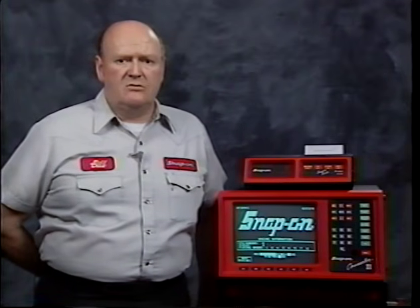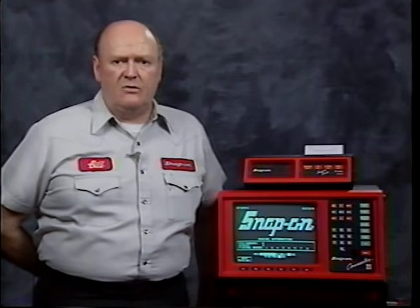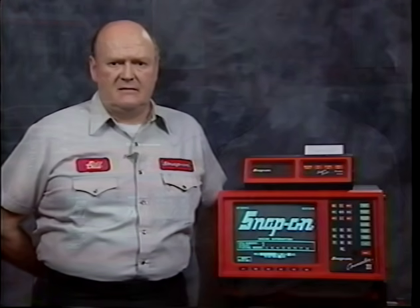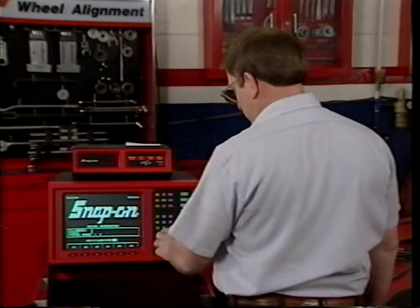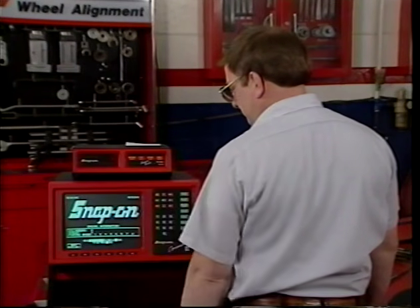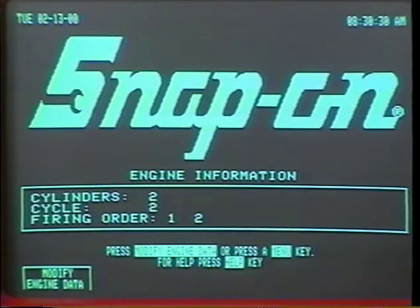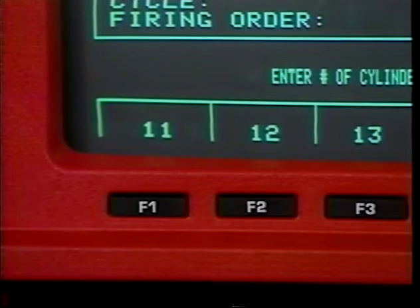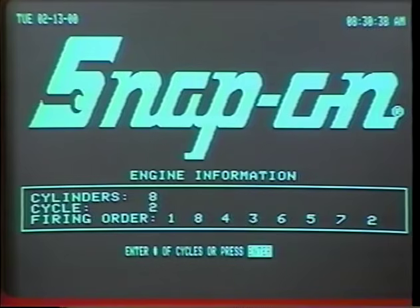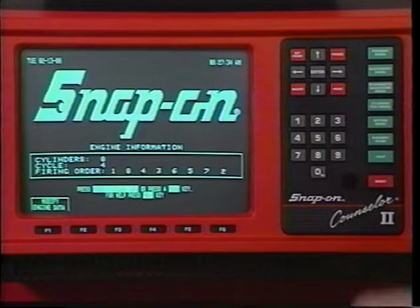The Counselor 2 will test virtually any vehicle on the road with engines ranging from 1 to 16 cylinders. The scope asks you to enter information for the engine you are going to test. Follow the instructions on the prompt. Press Modify Engine Data. Enter data with the numeric keys. The highlight cursor automatically jumps to the next entry. If the information on the screen is correct, simply press Enter.